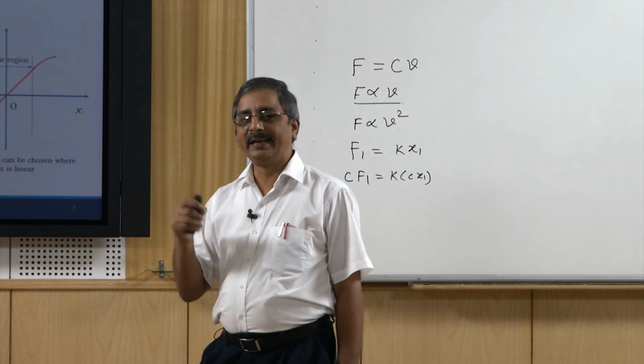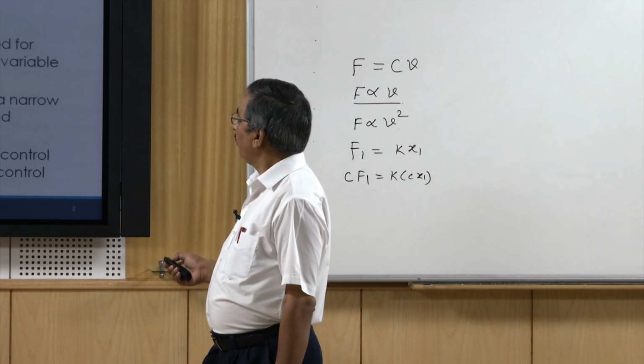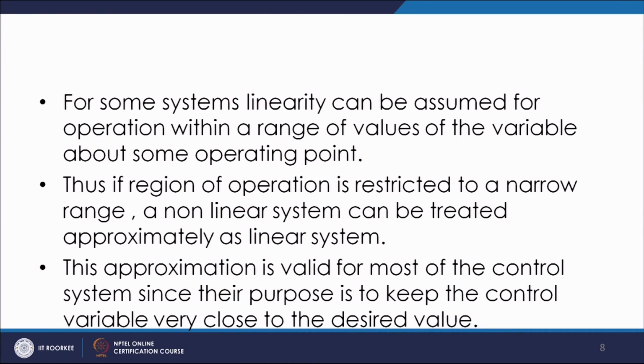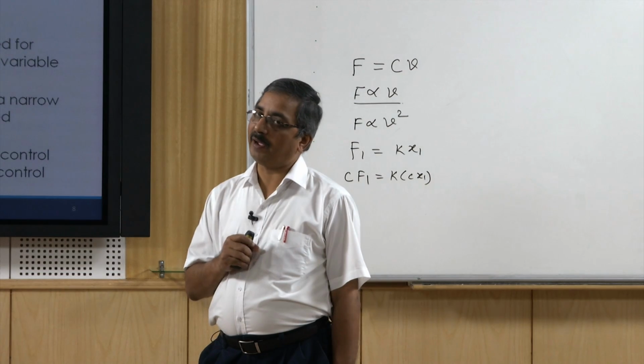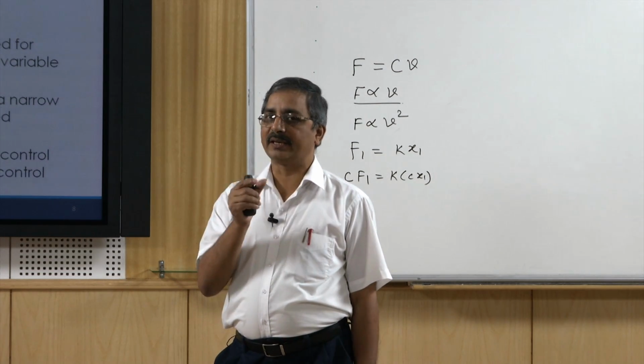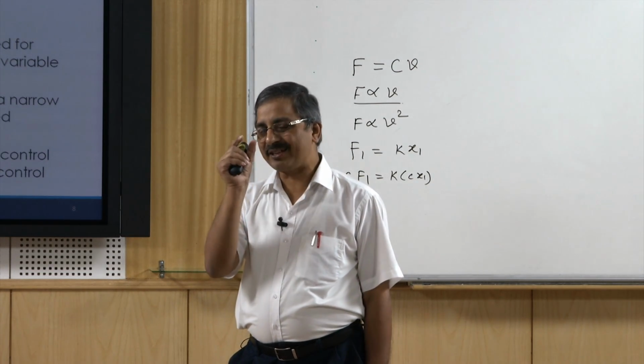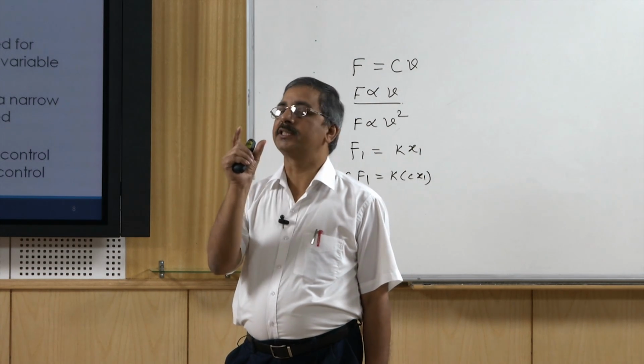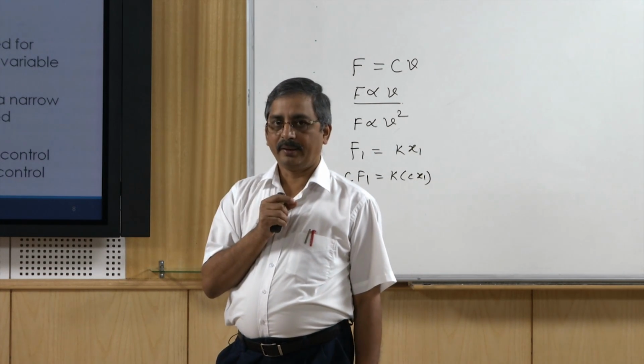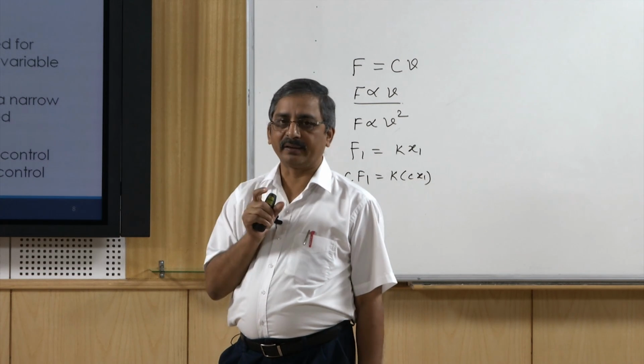It could be linear anywhere. Thus, if the region of operation is restricted to a narrow range, a non-linear system can be treated approximately as a linear system, as long as my operation stays in that small region where the system is linear.